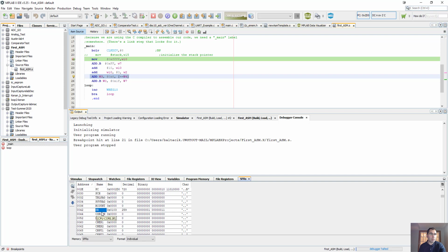You can see from here that the status register is 16-bit, and remember, at this point we really care about the first 4 bits, because those are the carry, zero, overflow, and negative flags. So you can see their status. If it is 1, the flag is raised, and if it is not, the flag is not raised.